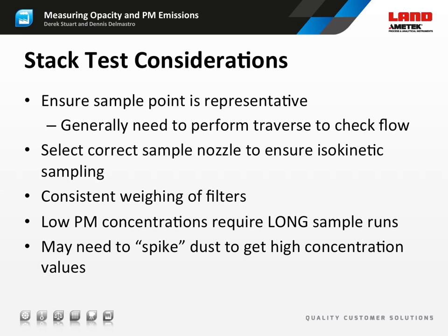Measurements of low dust concentrations can be very difficult. It takes a long time to accumulate a measurable amount of dust on the filter, and careful handling is needed to make sure the filters are not contaminated or damaged. There have been cases where a negative PM concentration was measured because the mass of filter paper lost in handling was greater than the mass of the particles sampled.